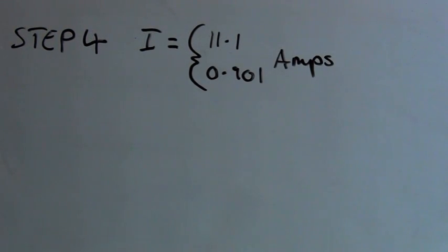Okay, so how is it that our circuit has two different currents? Well, actually it doesn't. The power of the light bulb is rated at a specific voltage, so only one of the currents is correct for the given light bulb. So let's calculate the voltage and resistance of the light bulb at each of these currents.